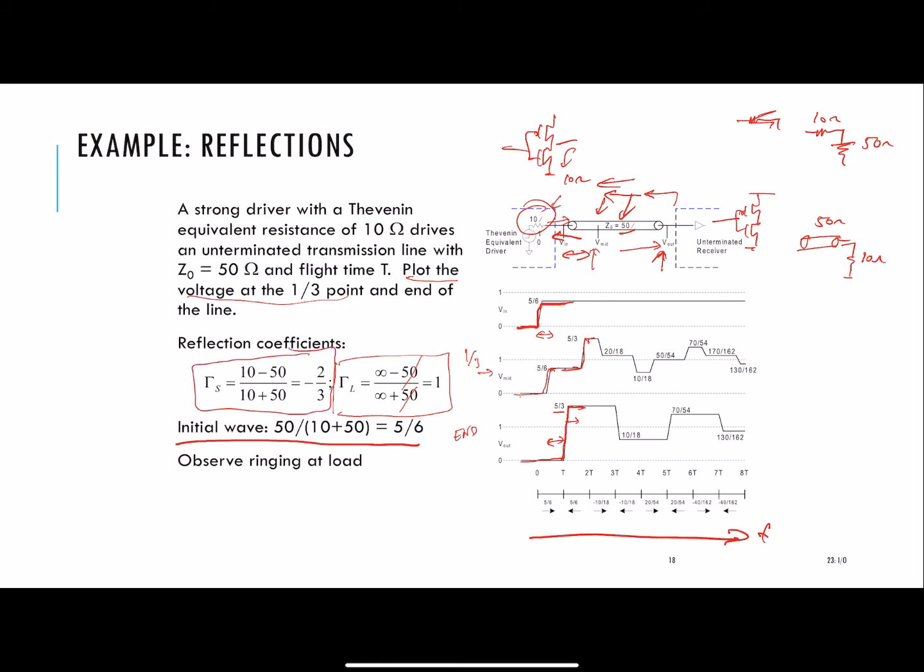So you actually go down by 2/3 from what you were. And then you relaunch that back into this point. Okay. And so on and so forth. You'll just keep going back and forth, back and forth. And if you look at just your output line, it'll do this kind of thing, which looks really familiar if you look at a high-speed input on an unterminated line.